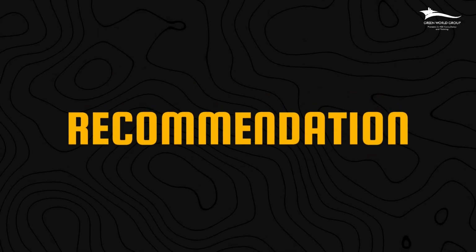And the last part is documentation. Finally, after doing all these studies, everything has to be recorded: findings, team discussions, then recommendations and responsibilities. Responsibilities means whatever we have suggested has to be done by some responsible people, so we record who those people will be. Due dates are also assigned, and a formal HAZOP audit report is generated, which will be handed over to the team. This document serves as the official record of the audit. So these are the 6 important points about the process of conducting a HAZOP audit.